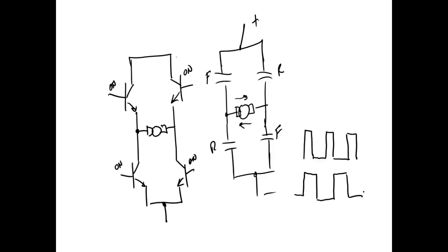This is the way everything goes. Because what we're doing is we're turning the transistors wide open. They drop very little voltage. We turn the transistors off. They drop all the voltage, right? But there's no current flow. So the devices themselves can handle a lot of current with very little loss. We can precisely control the speed of the DC motor.